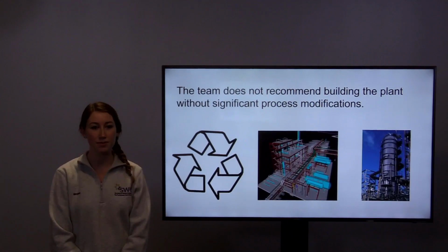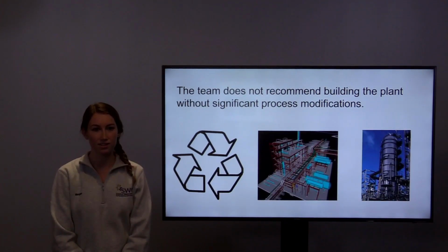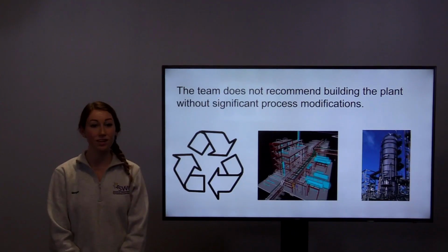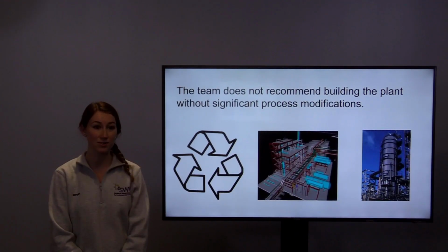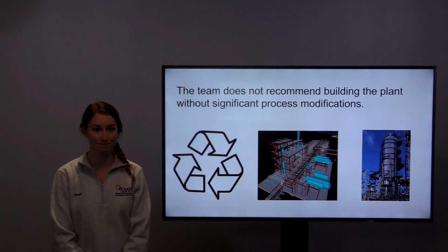Additionally, the team would recommend optimizing the utilities in the plant. Utilities is another large cost for the team. When creating the simulation, the distillation columns and several other units were designed such that they ran to give the desired purities and met the hard specifications for the project. In moving forward with plant design, the team would recommend seeking to optimize these utilities to decrease costs operationally. Currently, only 2 of the heat exchangers have been optimized to use other process streams rather than utilities to save costs. Other heat exchangers could be investigated to save on utilities, among other things, moving forward.